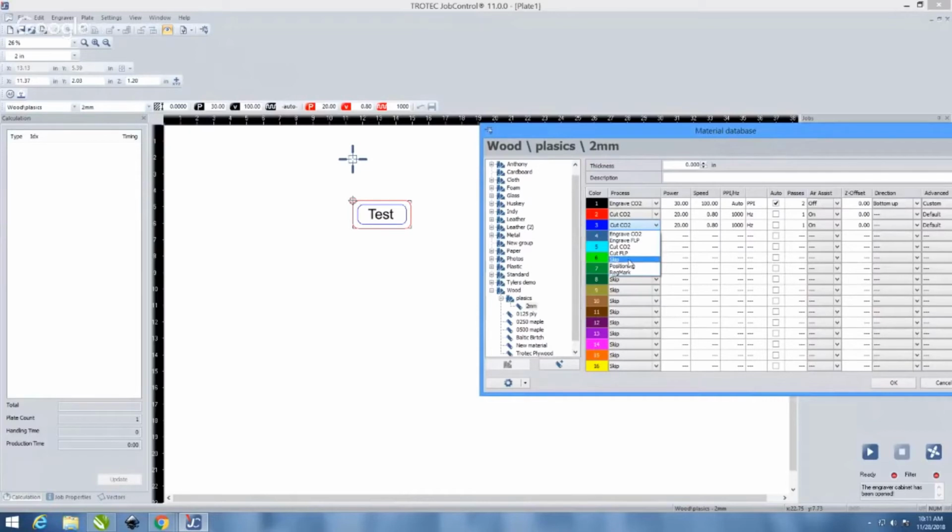What we're doing when we say kiss cuts is we're using the cutting with CO2 method, but we're just using a very low power here, very low. We just wanted a high speed. We just wanted to kiss the surface, so we can do let's say 10. And like Lev said, because we're not really cutting anything, we're going to use a higher speed, kind of like what we were doing within the engraving up here, and that's just to mark lines on our material. I just thought I'd cover that.